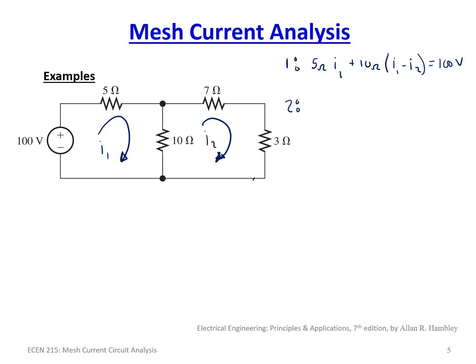So now we have equation number 2, same thing. We're going to start with the 7 ohm, kind of work our way around. So we have 7 ohms. Now obviously you can kind of see what you can do here. I'm sure you're already thinking the same thing. 7 ohms plus 3 ohms, I2. I could have combined that and simply made it 10, which is true.